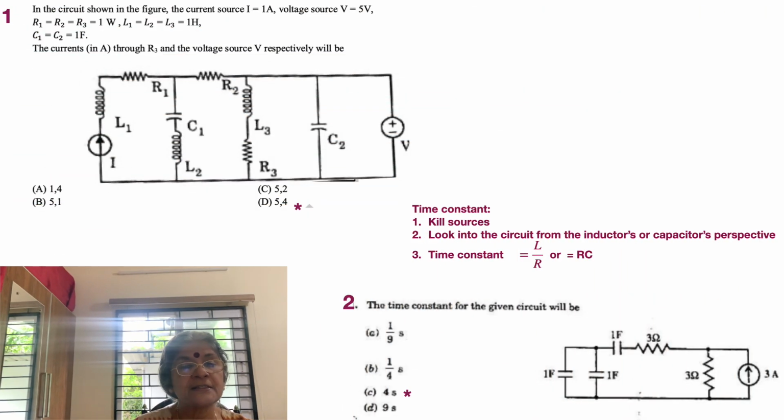Similarly, an inductor in the transient zone starts off as an open circuit and then it becomes a short circuit. There are several other aspects with respect to inductor and capacitor which were discussed earlier, which will also come consequently. So here we have a steady state situation wherein the DC sources have resulted in opening the capacitors and short circuiting the inductors. So if we follow the path from I, we see that there is a short circuit, and then there is the irrelevant resistor R1. When you look at the path through capacitor C1, that's open, so the current cannot progress there.